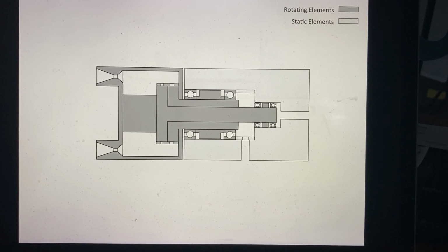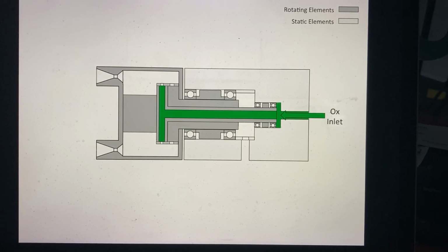The basic operation of the turborocket is accomplished by injecting propellant into the turborocket engine body. When the propellant flows in, it fills various plenums before entering the rotating assembly through a series of passages. This allows the oxidizer to pass axially along the shaft of the turborocket rotor assembly before turning radially and entering the combustion chamber of the turborocket engine system. It fills the injector ports prior to injecting oxidizer into the main combustion chamber.